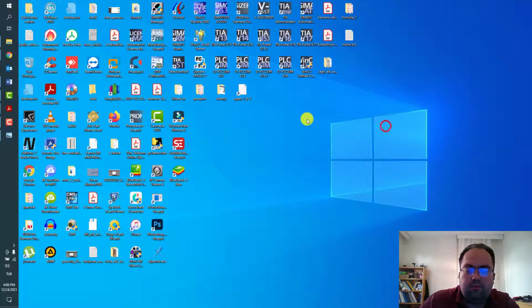So during the setup installation, there are some ways and packages for WinCC: WinCC Advanced, Professional, and Unified. For example, if you have already installed version 15 WinCC Professional, and in your project you are going to use WinCC SCADA software, in that case maybe you should install WinCC Professional, because only one instance is possible on the same hard drive.